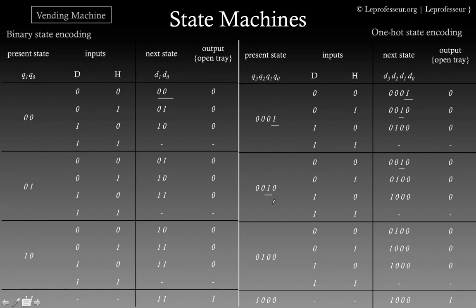We are in the Q3 state, the third bit is set, and in the Q4 state, the fourth bit is set. So we don't have to worry about all the other flops because only one bit is changing at one time, which is being used in our combinatorial logic or other places in the circuit. Remember that distinction between one hot encoding and binary encoding.